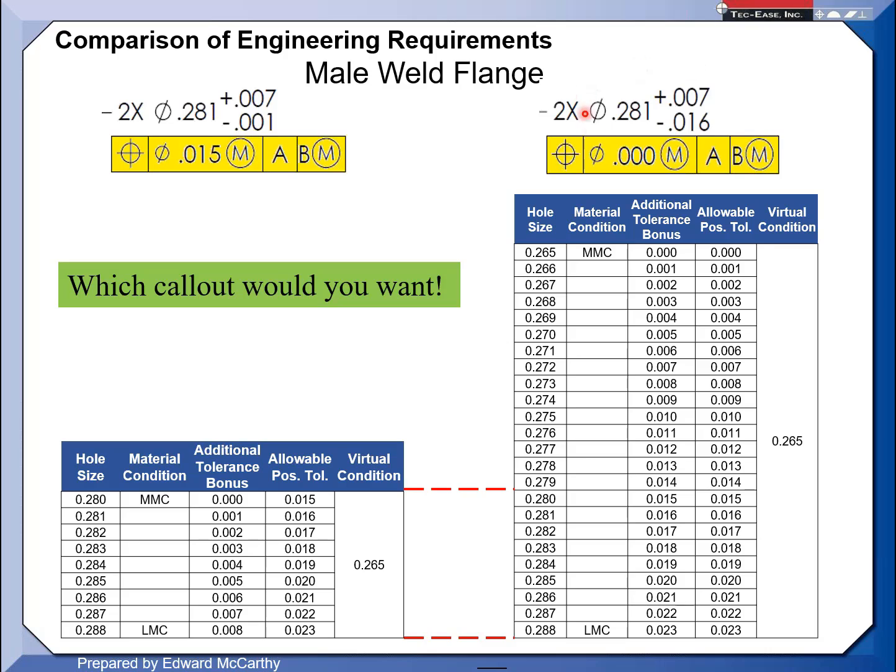Well, what winds up happening if you're allowing this here, and you have a knowledgeable manufacturing engineer, is that if they center the process, maybe they'll shoot for this size here, if they're trying to minimize the risk involved in producing the part, what we call producibility.